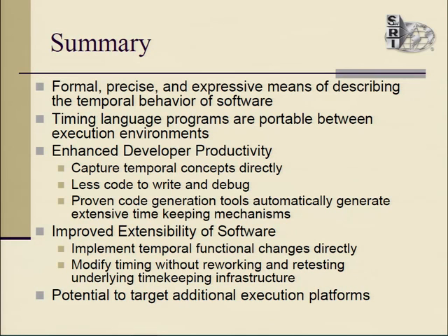So that would depend on, first it would depend on what hardware you're targeting. On an FPGA, it is possible to do 4 things simultaneously. In software, it's going to be simultaneous within the context of whatever the timing tick is for that environment. So for a C implementation, if you have to do 4 things simultaneously, you'd make one call to the timing module, and it would return those 4 things all as responses to that same call. So they would not be strictly real time in an actual nanosecond by nanosecond sense, but they would be real time and simultaneous within the context of the call sequence to the program. Okay.